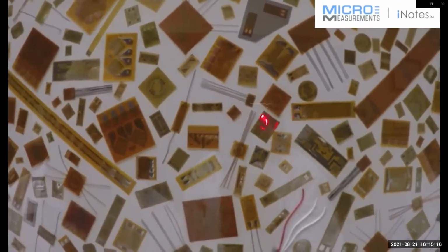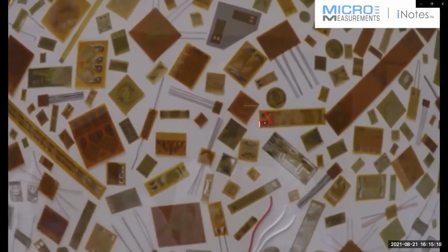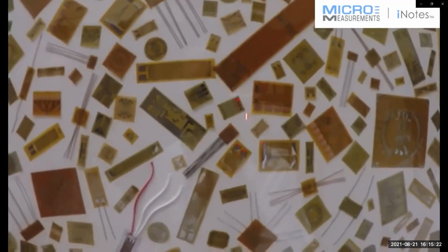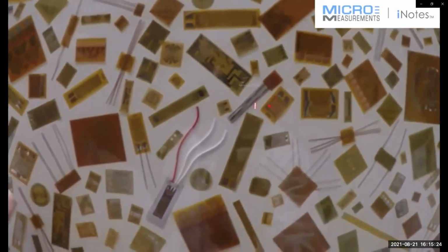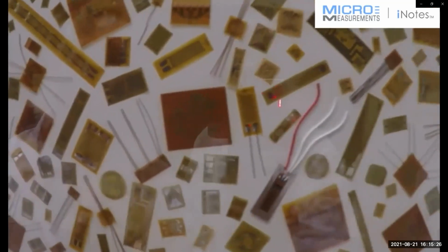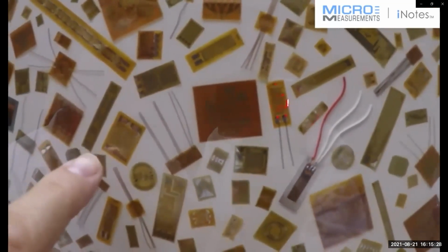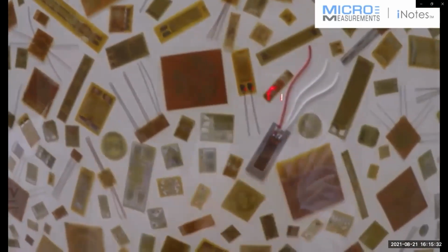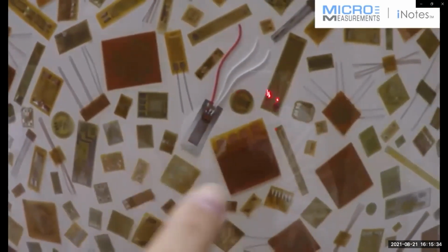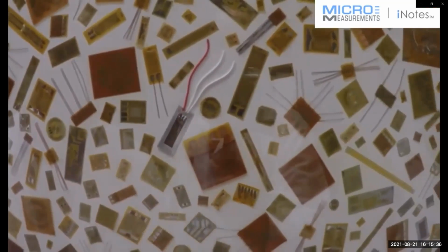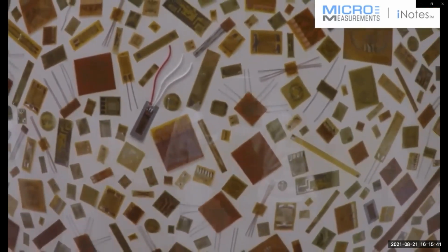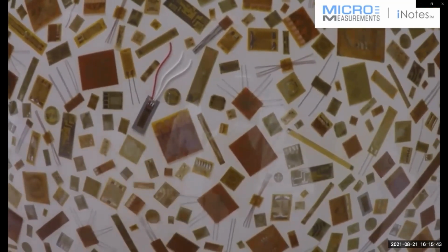And we've got not only the uniaxial gauges, we also have some examples of shear pattern gauges like this one. For example, if you're trying to measure torque on a tube or a shaft, that's a really good one to choose. This is another example of a shear pattern gauge. In addition to that, we also have some T rosettes and rectangular style rosettes and even delta rosettes.